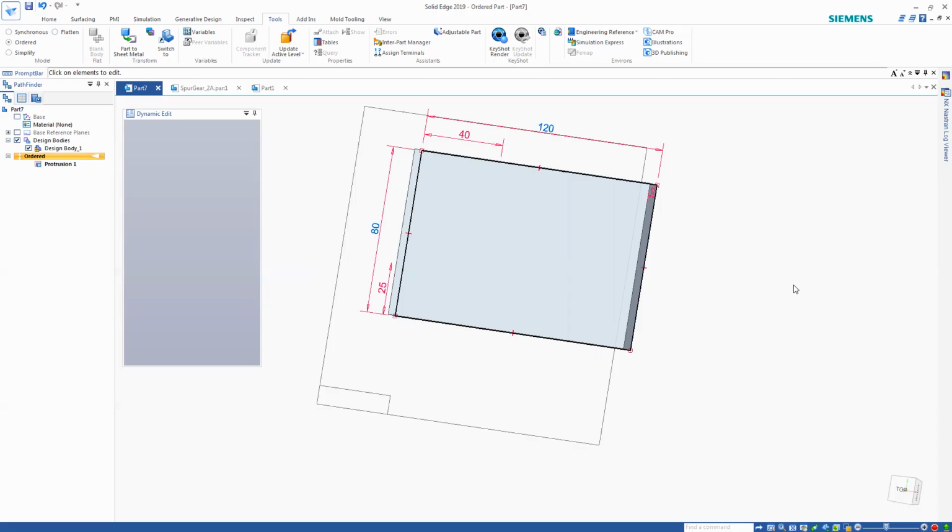But here are the parametric relationships, where you can relate not only this one with anything else. This is within the part, and you can do it between parts as well. So you have the gear wheel and the shaft. The gear wheel should go and sit on a particular step of the shaft. So these two diameters need to be matched. So during a calculation, you realize that the shaft diameter has been updated, right? But at the same time, the gear wheel's bore diameter should also be updated.